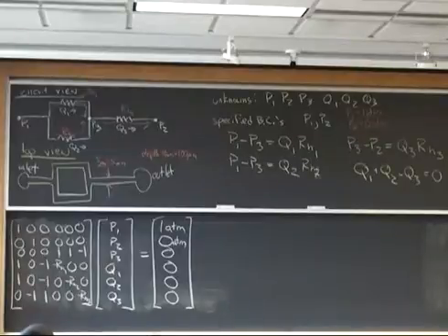Yeah, Marie. Well, of course, it depends on how we define the units. And so certainly if we define inconsistent units, then we'll either get no answer or the wrong answer. What you say really does hit at the key problem. And the key problem is that if you use SI units like you've been taught, then you'll find that these hydraulic resistances are not going to be close to 1. In fact, they'll routinely be 8, 10, 18 orders of magnitude different from 1.